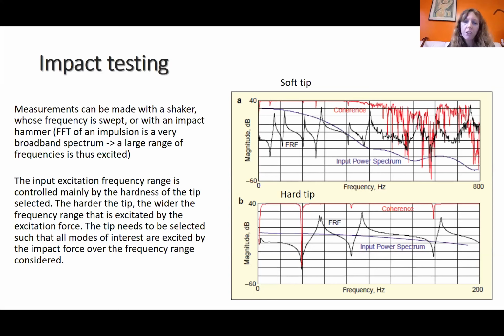But on the bridge, it's kind of fine. And so we usually use a hard tip. Actually, what works very well is when you put a little plastic cap on it made of plexiglass. That makes it very hard and flat, but doesn't damage the violin as much as the metallic hard tips that are usually distributed with such small impact hammers.